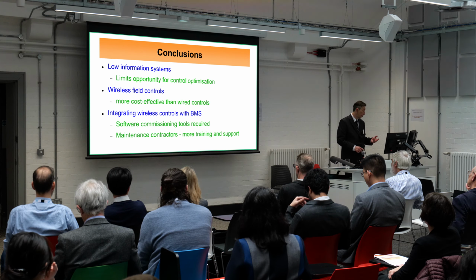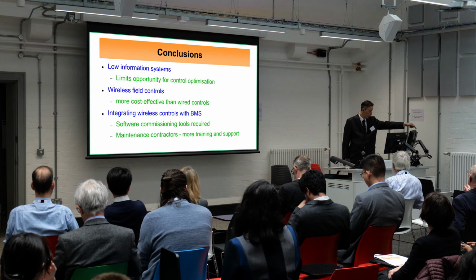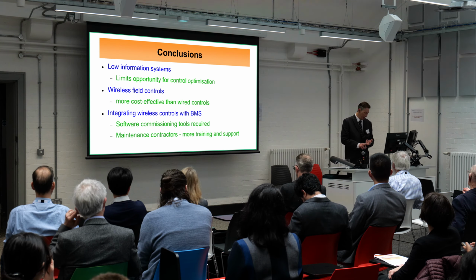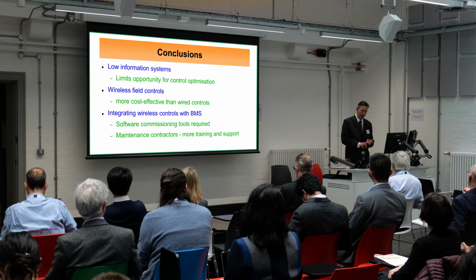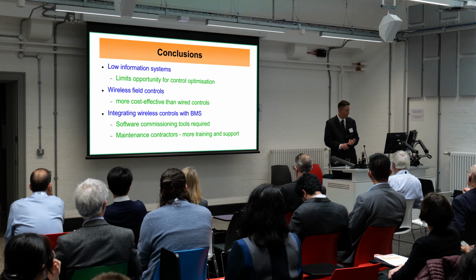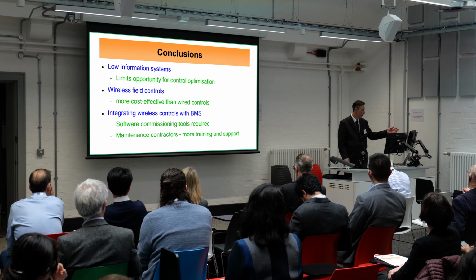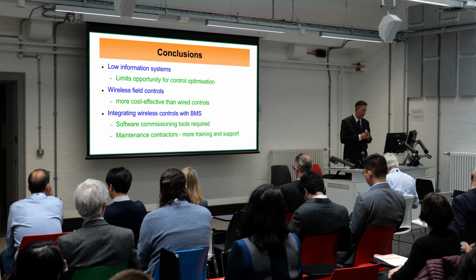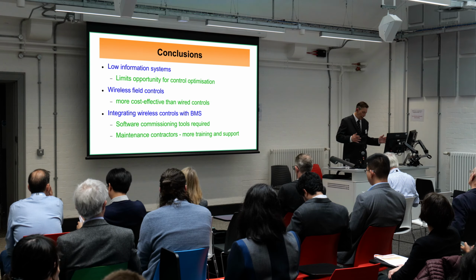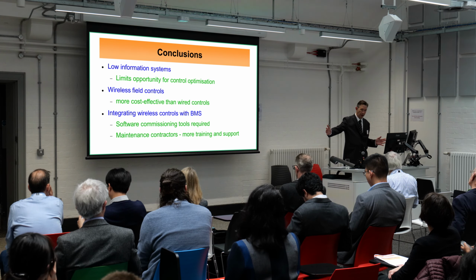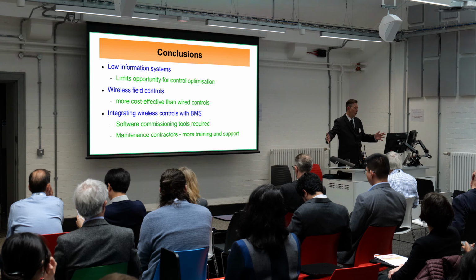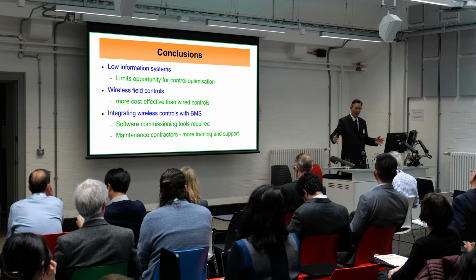And when we're looking at things, particularly where we're interacting with a mechanical system with smart TRVs, who maintains them? Because your average maintenance contractor with his favourite weapon, a spanner, is not maintaining these devices properly. You know, we're putting very, very intelligent controls in all sorts of equipment in a building, but if it's commissioned and made very energy efficient, for the rest of its life it has to be that energy efficient, otherwise it doesn't control it. But a standard mechanical contractor is much more likely to not maintain these devices correctly and result in us losing all of the efficiency once it's handed over.